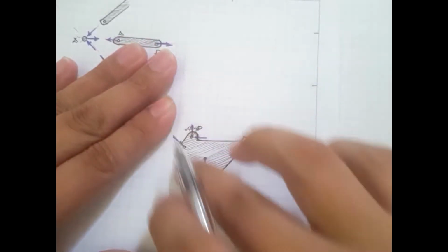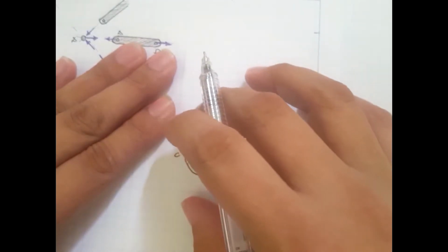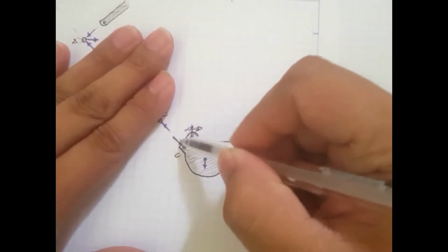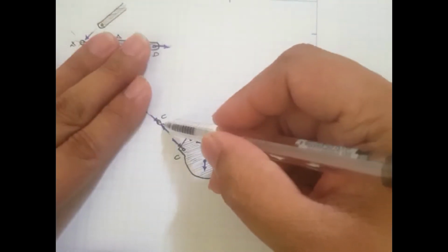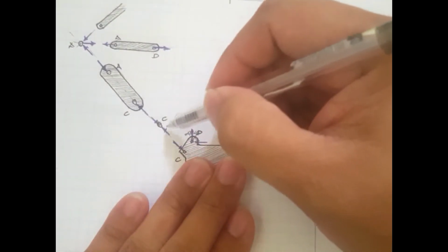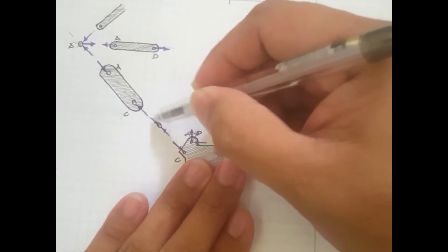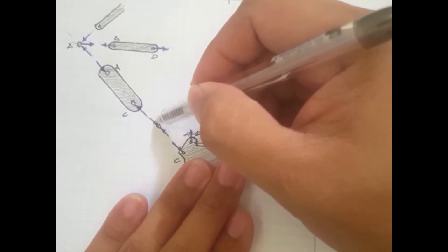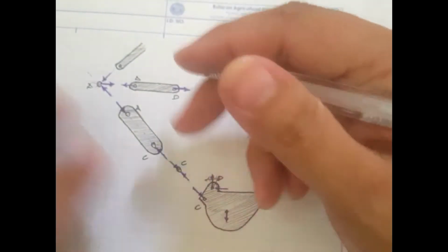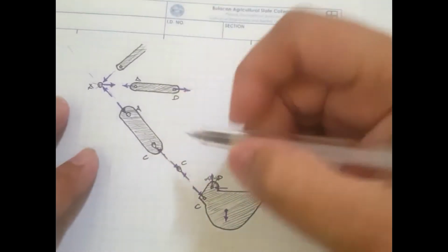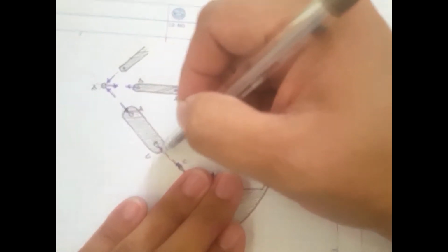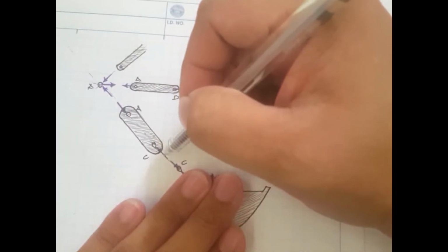Once we've applied the equilibrium equations in this assembly, and we can find this force, then we can translate this force to the joint right here. If we apply the equilibrium equation at the joint, this force will simply be equal to this force. But you would notice there's a difference in the direction, because with respect to this link, this will be a reaction force.